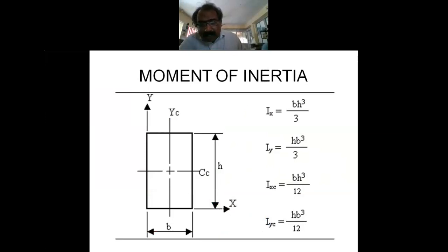Similarly, in columns, I already said the moment of inertia. The moment of inertia is the initial for any structural engineering member. Inertia is like your father. Whether you like your father or not, your father will safeguard you. Similarly, in a member, if the moment of inertia is stronger, the member will not bend or deform. For different sections there are different moment of inertia formulas: rectangular, circular, which is pi d to the fourth by 64, and triangular columns have their own. So students should learn moment of inertia well, because that is the very basics for all of civil and structural engineering.